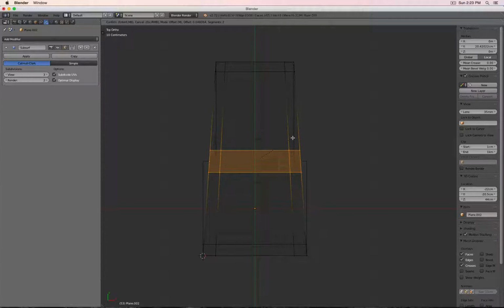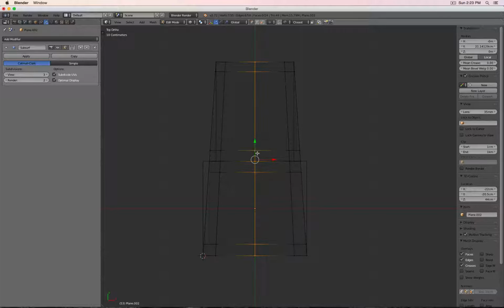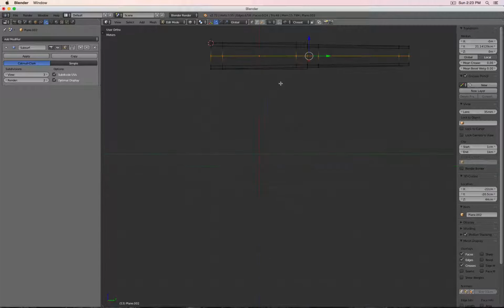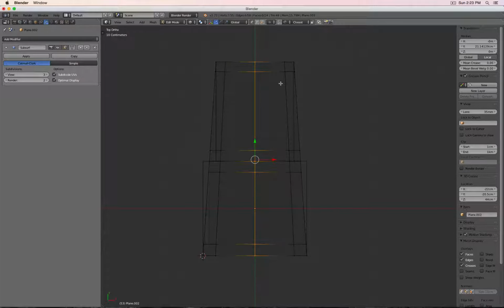So you see I'm basically unbeveling this line into two lines, and with moving my mouse wheel one time I have the midline back. So I'm basically having three lines with which I can work to create a fillet. And maybe I create a midline, press 0 and enter. So actually I can at one point use the points on this midline to, for example, vertically move these points up and down to create a little bit of kind of like a dipped down surface for your hip to rest in. Okay.